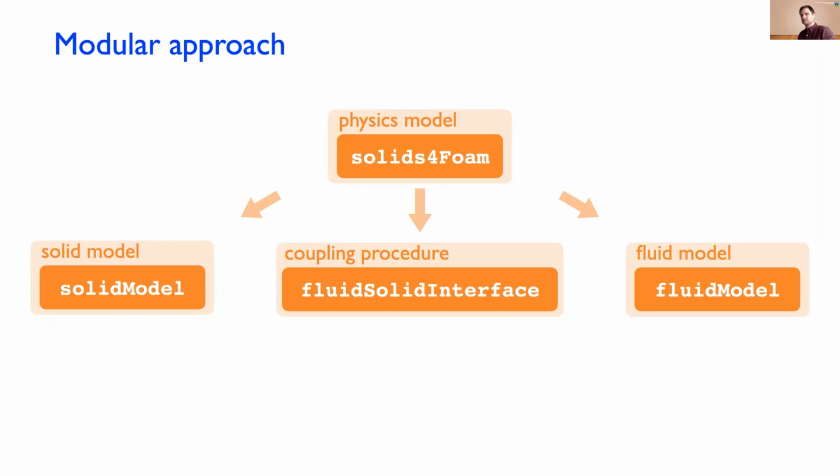If you want to do that, the traditional OpenFOAM approach would be to make a new solver called pisoSolidDisplacementFsiFoam or something like that. And there are solvers like that. I know I shared one called icoFsiNonLinearElastic something. Or there was fsiFoam in a few different versions. They have a hard-coded version of the fluid solver and a hard-coded version of a solid mechanics solver. So if I want to make a new solver using a compressible fluid formulation, I actually have to copy a lot of code and make an entirely different solver.